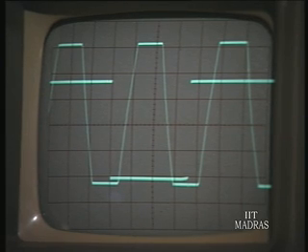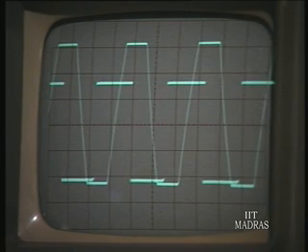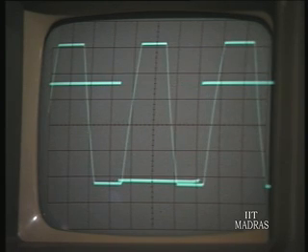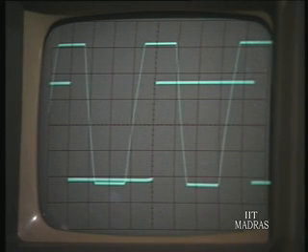Please go to the other side. Yes. See, you see the phase shift changes from 90 degrees also, and it is going to become very nearly equal to 0 on one side and equal to pi on the other side, at which it will go out of lock. And go further and show them the harmonic locking. Further, let it go out of lock and then further you go on the same side.